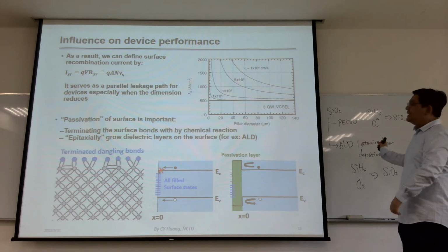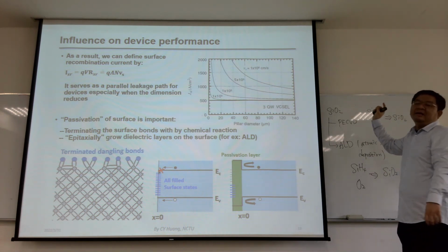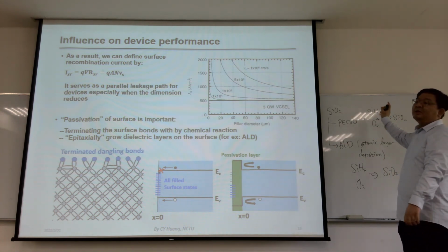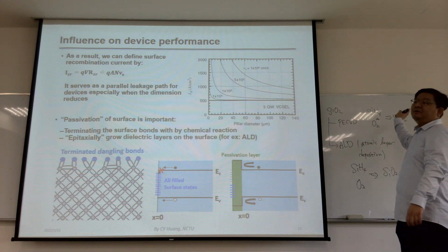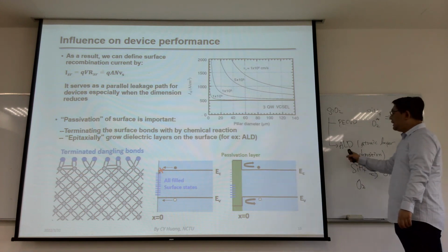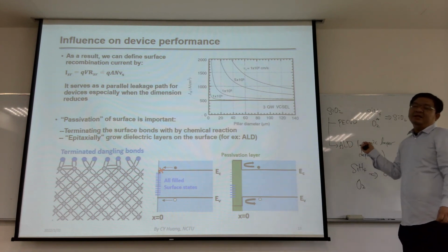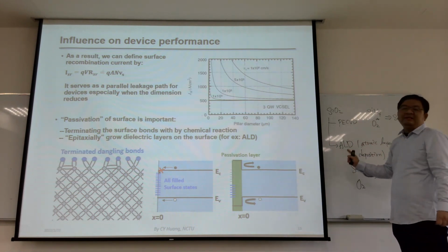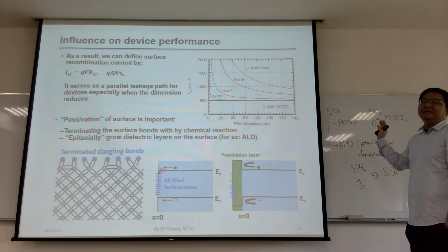Since you are flowing two gases one at a time, you might get a 100 nanometer film in a few minutes, or 10 minutes is already pretty slow. However, when you're doing aluminum oxide atomic layer deposition, depositing a 30 nanometer film is almost impossible.